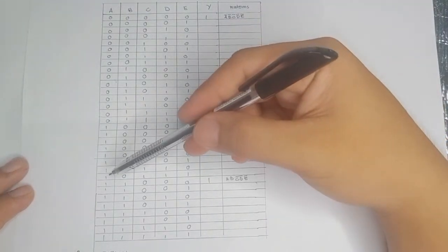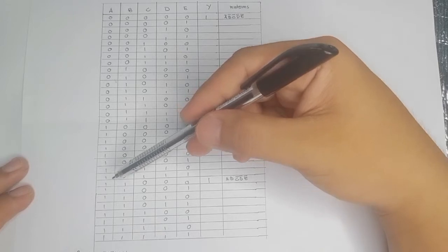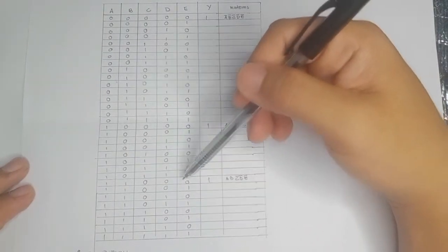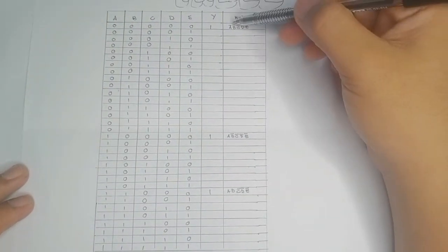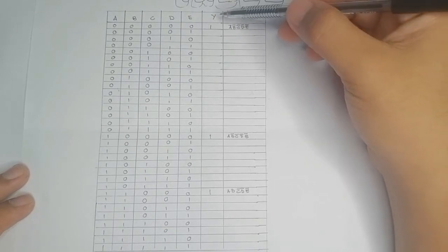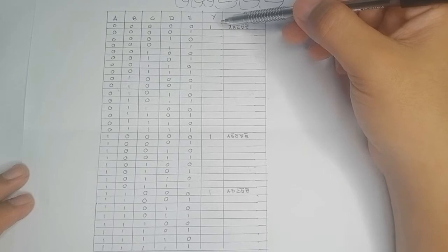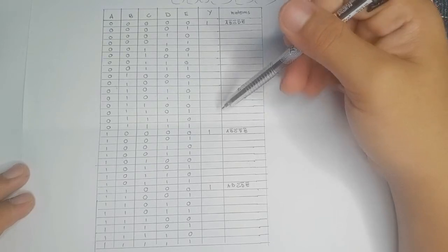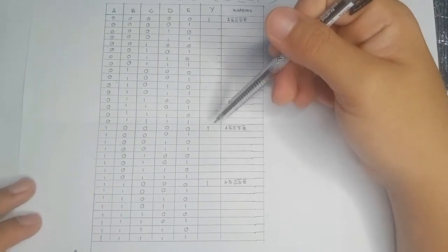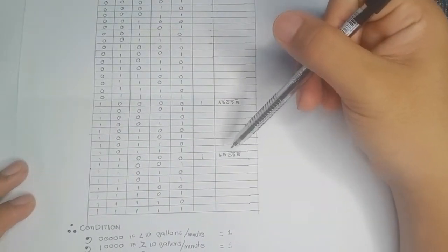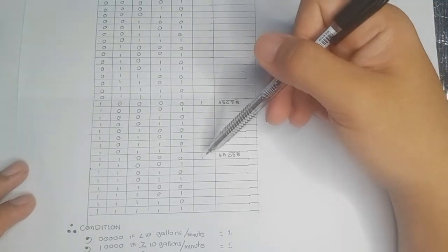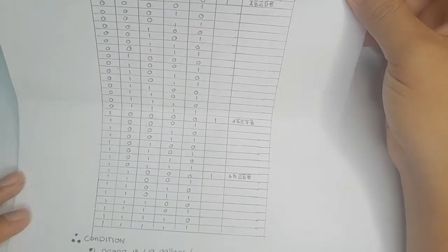And next, if the first and second digits are 1, then we can have an output of Y if all the rest are 0. So the minterms are: not A, not B, not C, not D, and not E. In order for us to get Y as 1 as an output, here we have A, not B, not C, not D, not E. In order for us to get one output, and the last is A, B, not C, not D, not E, in order for us to get our Y equals to 1 as an output. So with the minterms, I simplified it already, and